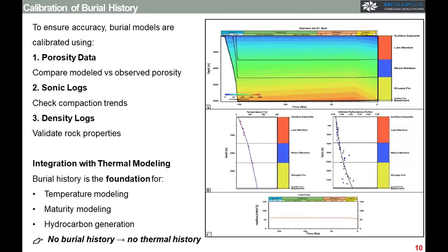If you have a pore pressure coming from the sonic, it's better. But if you don't have this point already in the 1D model, it can estimate the hydrostatic pore pressure and overburden. But this is calibrated from your data from the wells. But you need to add more data for it. And from this compaction trend, you can estimate the porosity, the total porosity.